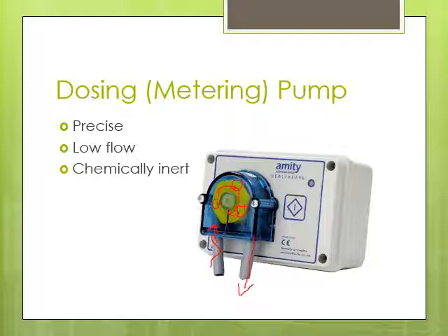If you've looked at the dosatron, or the dose meter that is on the NFT lettuce in the college greenhouse, you'll remember there's little motors that whine every once in a while. Those are peristaltic dosing pumps for dosing A, B, or acid into the lettuce solution. They're very precise, but they're a fairly low volume. They're good for a small system, but for large ones, the diaphragm clicking pumps that I talked about before are more commonly used. Again, because it's not touching the component parts, it's not corrosive.